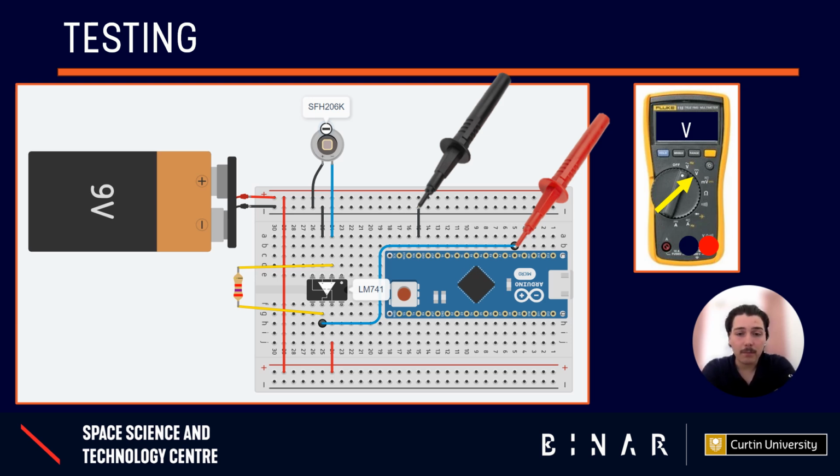Also make sure that pin 3 is connected to ground, which is your non-inverting terminal, and also pin 4 is connected to ground, which is your negative supply voltage. And then lastly, make sure that pin 7 is connected to your positive supply. Once you've got all those connections in, your circuit is as intended, and if it doesn't work, I'd slowly start replacing components. I'd use the multimeter to check to see if my battery has voltage.